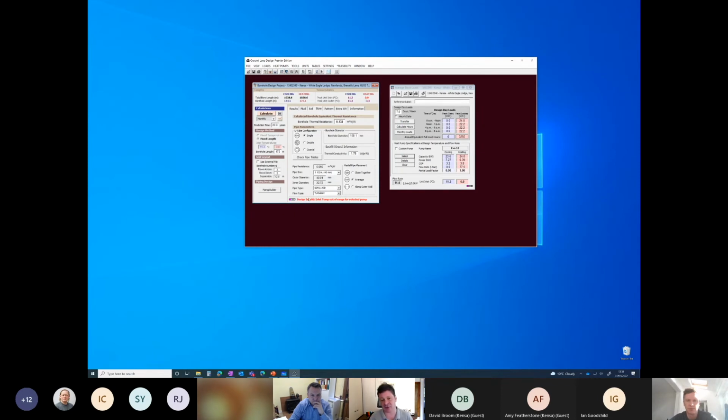And I'll talk about hydraulics of systems next time. So is it a laminar flow, so a smooth flow, or is it a turbulent flow? And we'll talk about that next time. Diameter of boreholes, grout conductivities, and so on. We then give it a pattern. So in this instance, it's a simple 3x2 grid on a 12-meter spacing. And we then hit calculate.